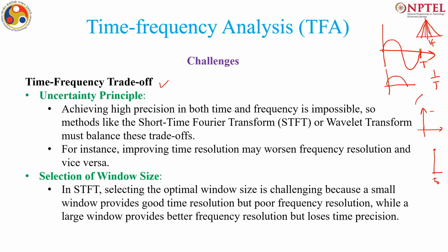And if I go with infinite cycles, then I get a precise spectra at that point. So, the question is that if I localize too much in time, I do not get the exact frequency, I am very much uncertain about frequency. But if I increase the time plot, I am very much certain about the frequency, but then I am uncertain in time, because in time I am getting a wider window, right.